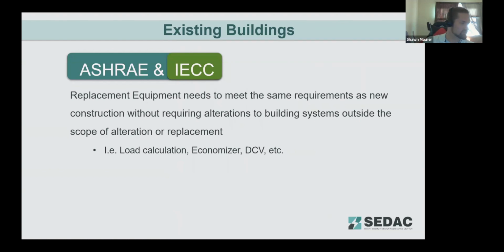But that is true. We have run across geothermal applications where, particularly in extremely cold weather, those bore fields get shocked with that cold water, and the pumping systems have to turn down temporarily and then restart. And that causes some delays in recovery rates and stuff. But yeah, I haven't noted that either code has specific exceptions for geothermal systems for those setbacks.